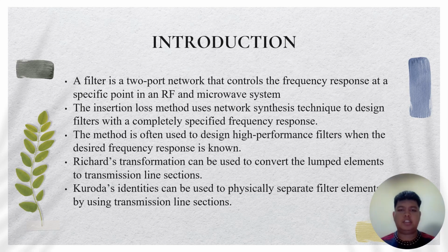Okay, so this is the introduction. First, a filter is a two-port network that controls the frequency response at a specific point in an RF and microwave system. The insertion loss method uses network synthesis technique to design filters with a completely specified frequency response. The method is often used to design high-performance filters when the desired frequency response is known.